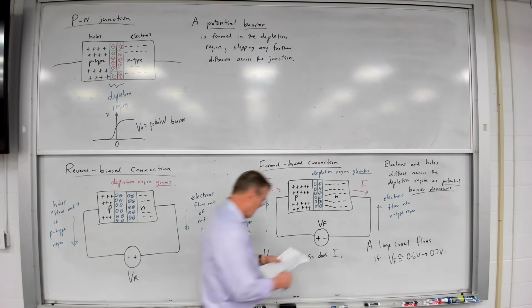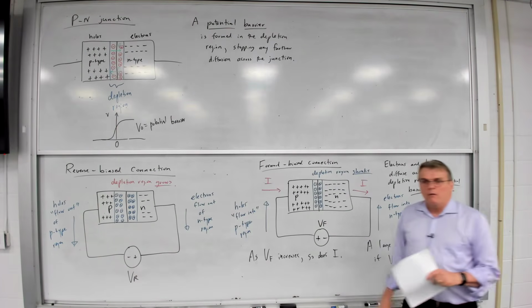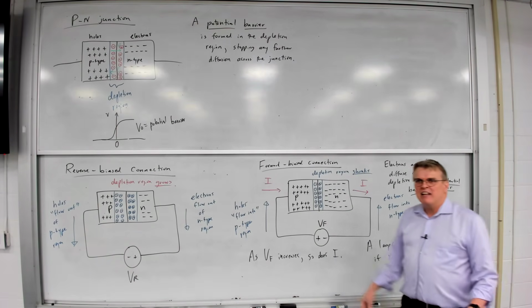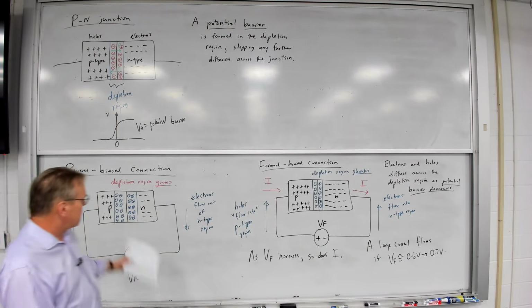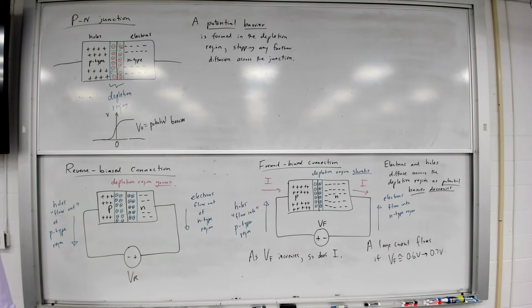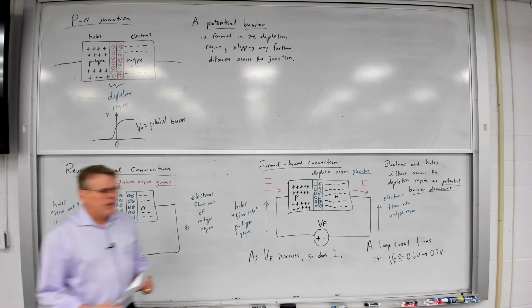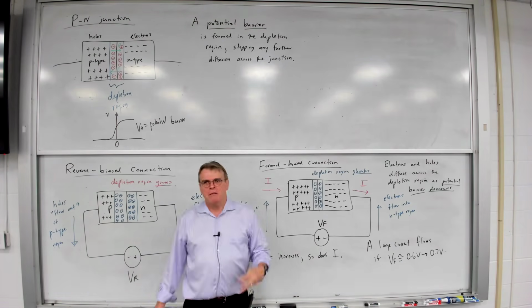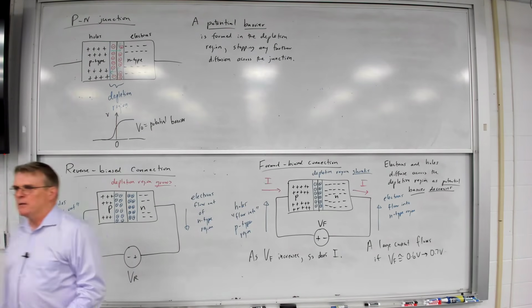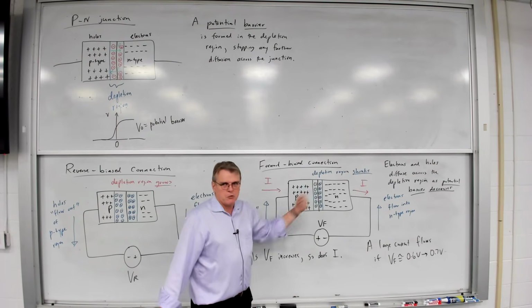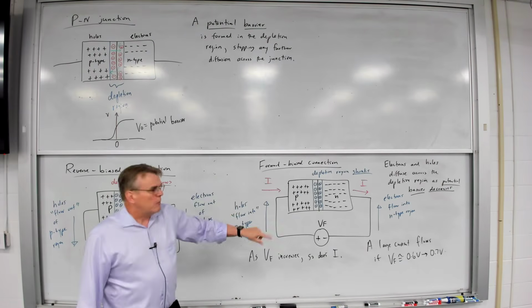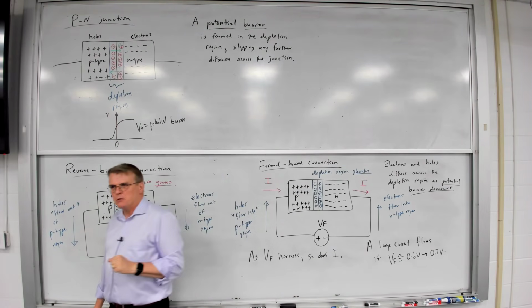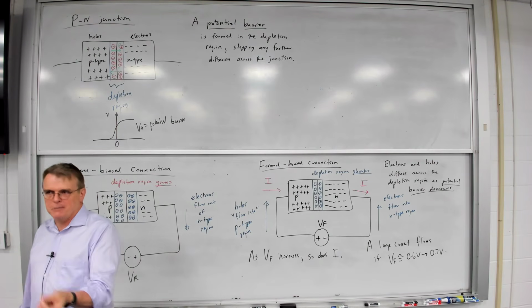So we see that in forward bias, we can have milliamps, amps, tens of amps, hundreds of amps if we wanted to. In reverse bias, it's going to be small: picoamps, femtoamps, nanoamps, very, very small currents versus very large. And it only takes a forward voltage of about 0.6 to 0.7 volts to start that current flow, just enough to overcome the initial potential barrier. And incidentally, different materials, different semiconductors will have different potential barrier values. So silicon classically has about 0.6 to 0.7.